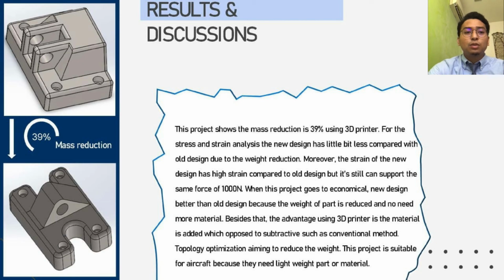When this project goes to the economical side, of course, the new design is better than the old design because the weight of the part is reduced and no more material is needed. Besides that, the advantage of using a 3D printer is that material is added, as opposed to subtractive, such as the conventional method, using topology optimization to reduce the weight. This project is suitable for aircraft because they need lightweight parts.